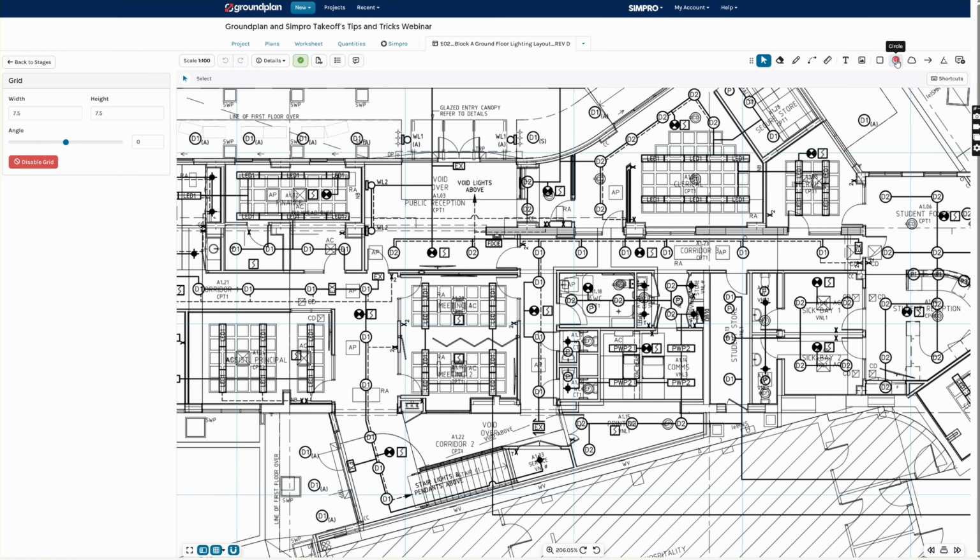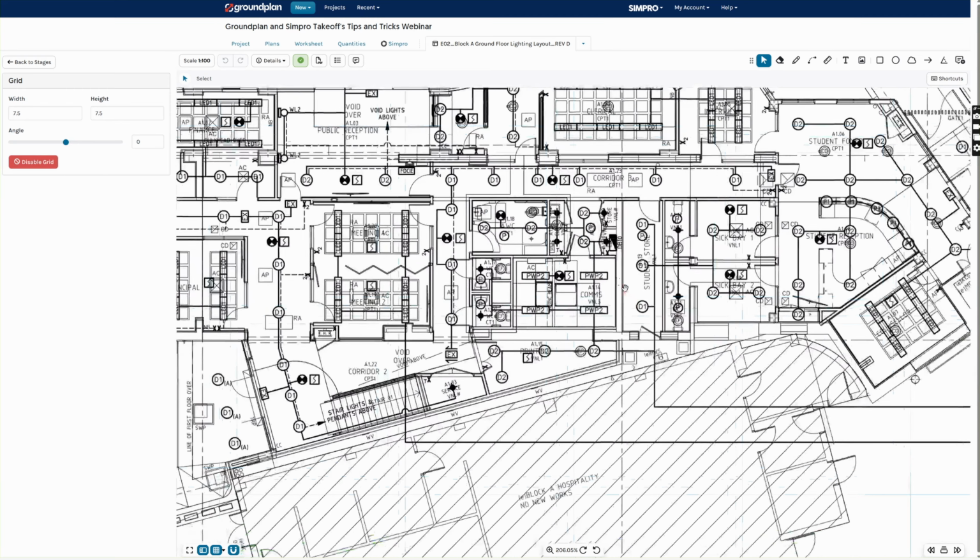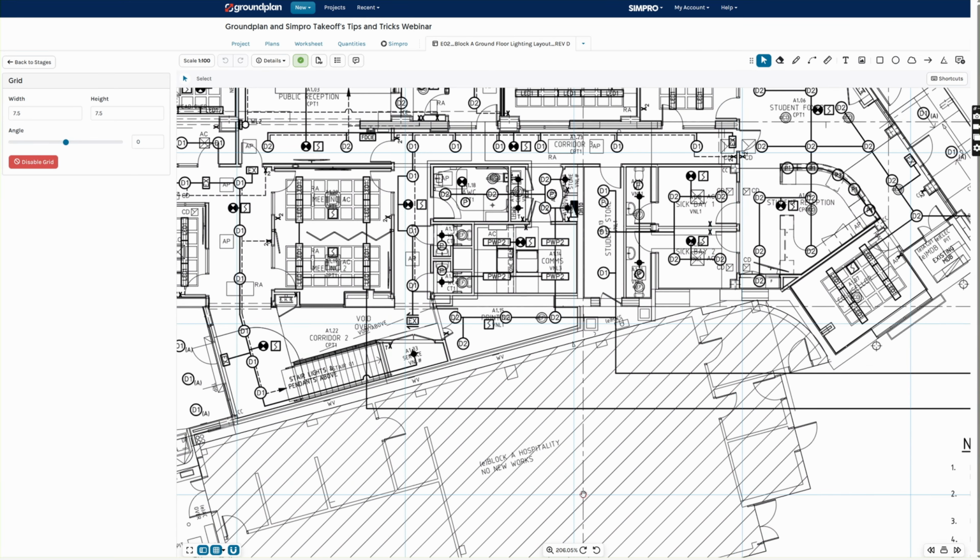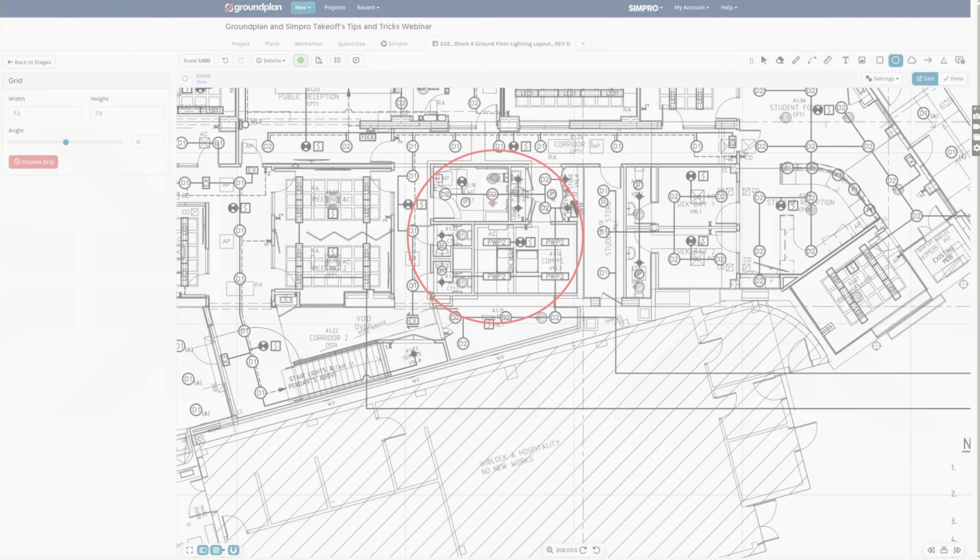Using our circle tool, so what I'd do is I'd make sure that that cross of the grid was lined up on the smoke detector. We can just grab our little circle tool, and then that will give you your 7.5 circle. And you can probably just put them in the middle there, I think. The other way may be sort of using the ruler tool to give you a guide, but a lot of my guys are using the circle tool to sort of then go from that side because of the grid that you've got option-wise.